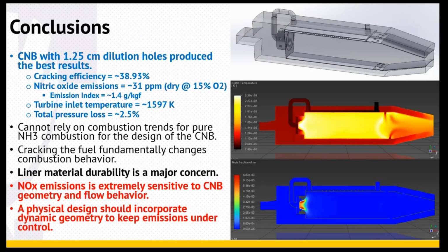So for a jet engine, for instance, this combustor was designed for takeoff. This design is good for the takeoff conditions that we've analyzed in our system modeling of the clean engine. But a jet engine ascends through the atmosphere, goes to cruise, and comes back down. There are going to be wide swinging changes in the conditions going into the combustor. So to keep your emissions low, the combustor is going to have to adapt to that, because this design might give you horrible emissions at cruise, where I did the best at the ground level.